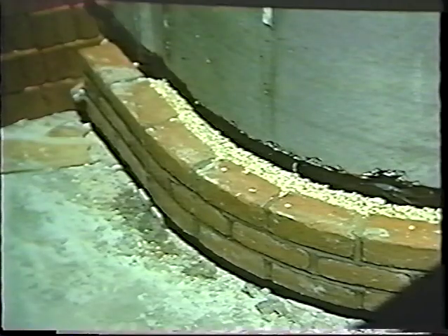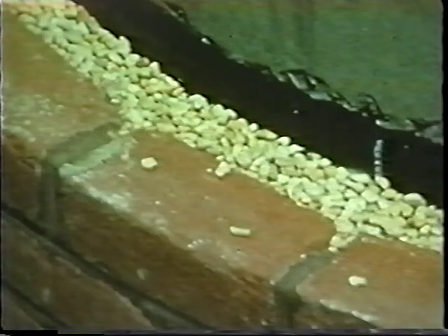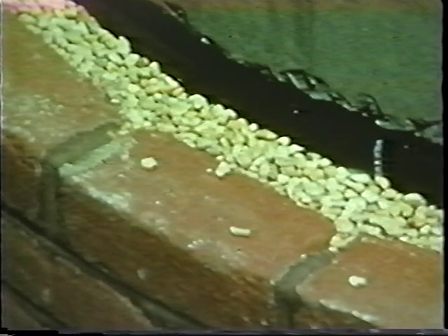In some instances, the bottom of the airspace is covered with a granular material like pea gravel or plastic netting. This material will keep the weep hole from being blocked by mortar droppings. Any material used should be free from contaminants such as salts. The proper performance of a wall is determined first by the wall type used and second by proper construction of the wall. If all these procedures are followed, complaints will be kept to a minimum.